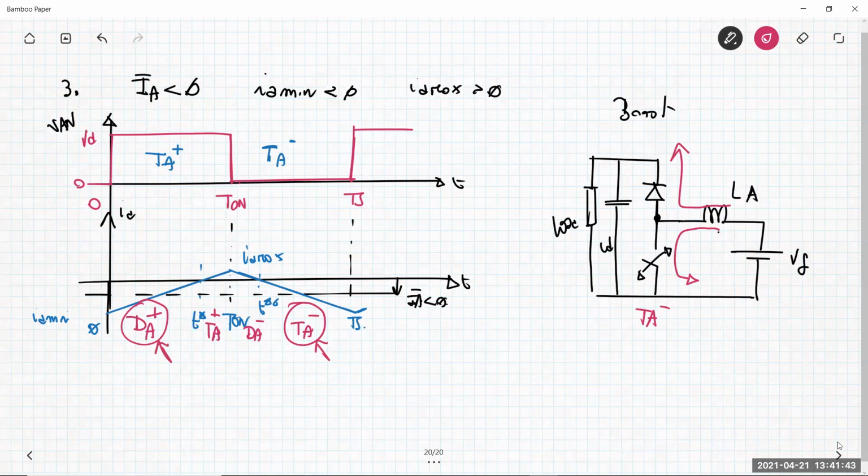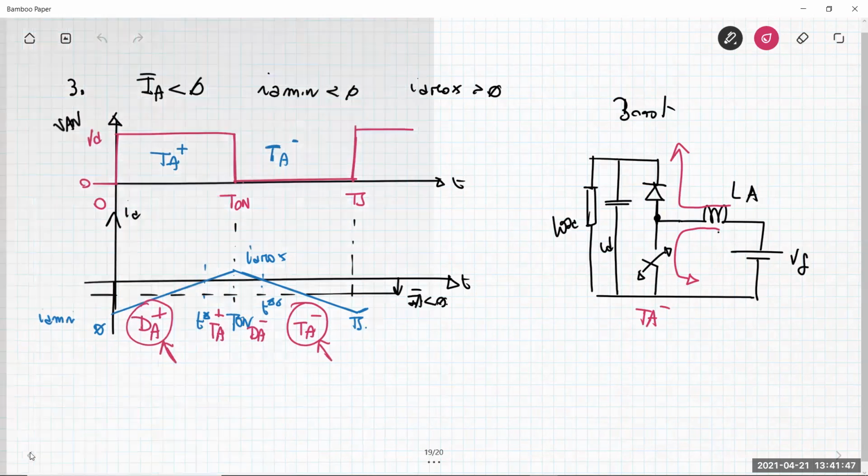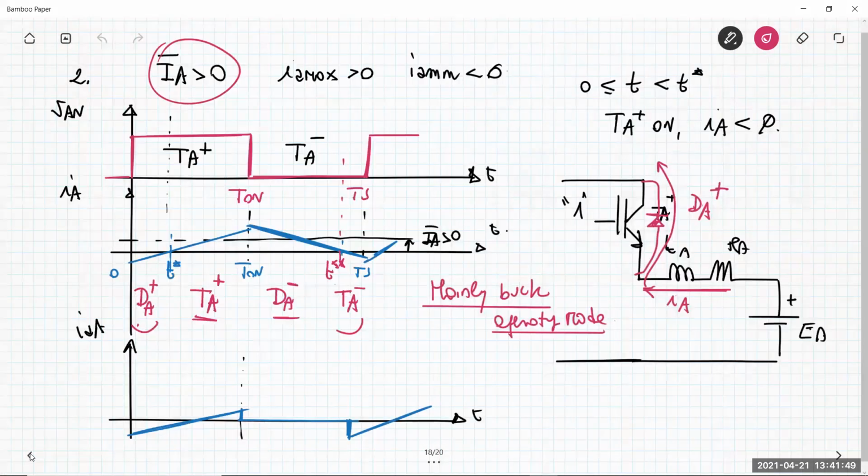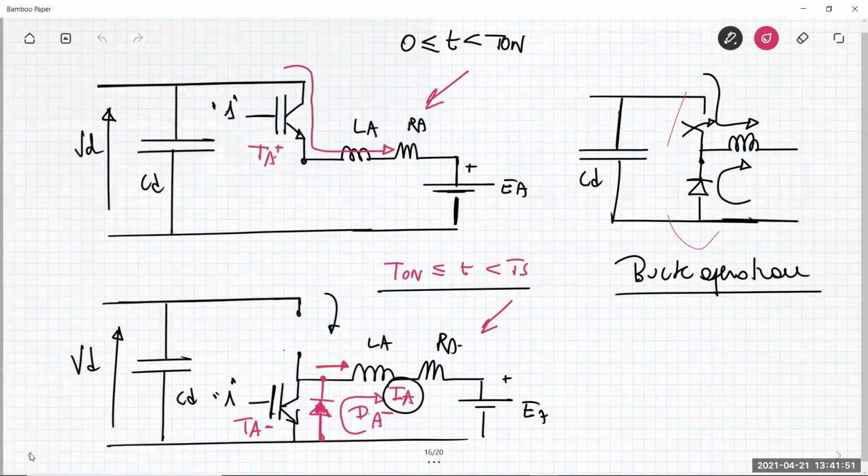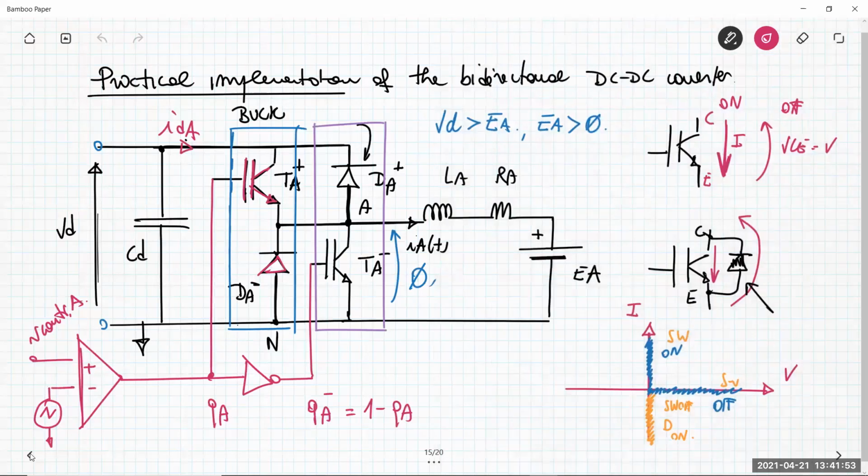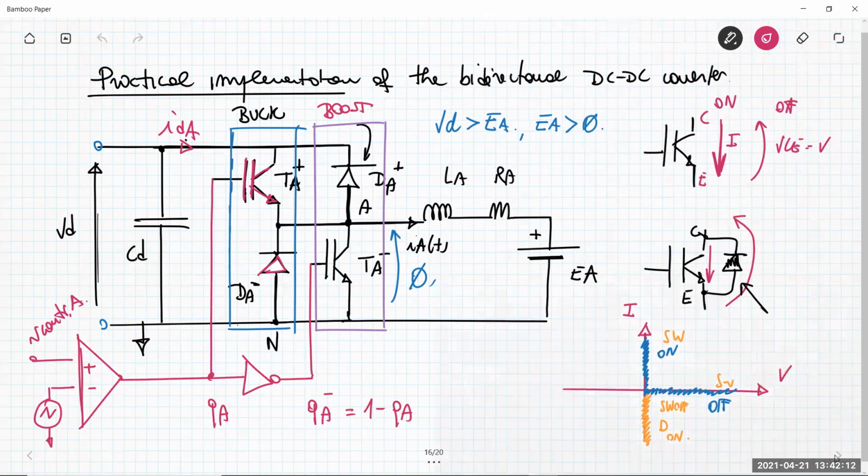So these 2 components are the components you must use if you want to derive a step up DC-DC converter. So it is exactly what's inside this purple box here. I just separated the two kinds of device to highlight and stress the presence of the buck and a boost converter in the same switching power pole.